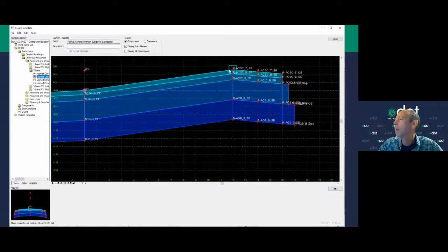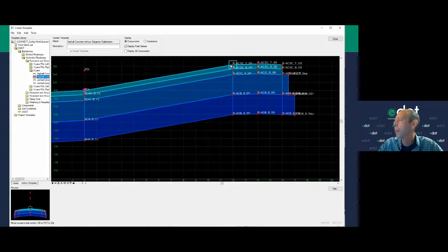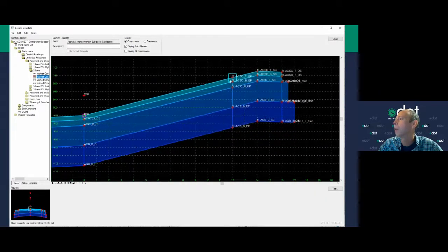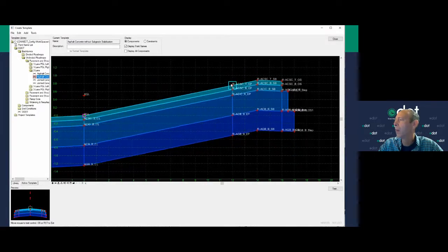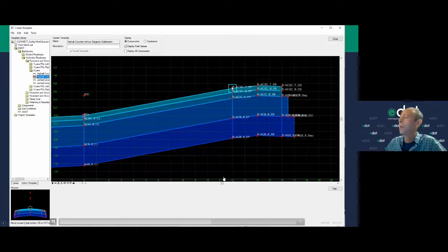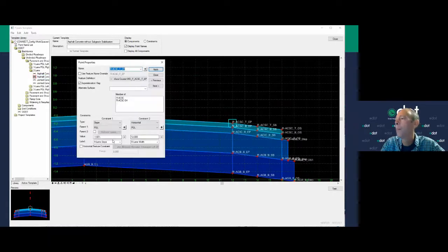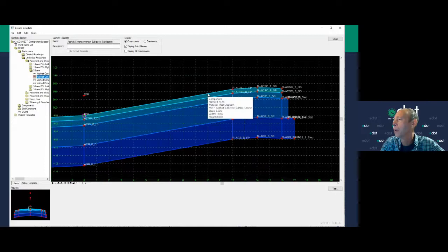As I get up and hit that 5%, somewhere in here, then that center point starts to raise up. And when I hit 6%, then that slope will be 6% and they're equal. So that's the current behavior on that. And I probably do one more thing in this video. Just to check it, I'm going to edit the edge of pavement point and change the slope to 5.5%, so it's halfway through that 5 to 6% transition. And when I float my cursor, it'll show me the slope.